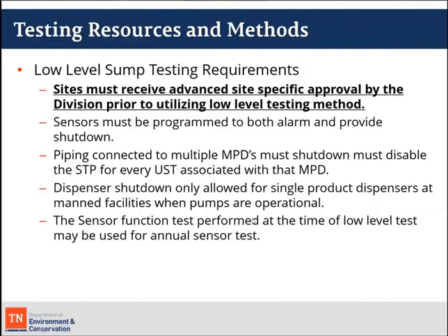But for most UST setups, where you're having multiple products dispensed through multiple dispensers, then you're going to have to do a shutdown of your STPs associated with those dispensers. A sensor function test needs to be performed at the time of the low-level testing.